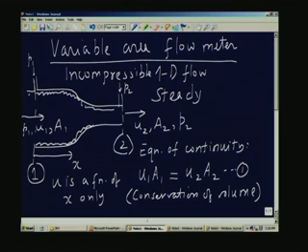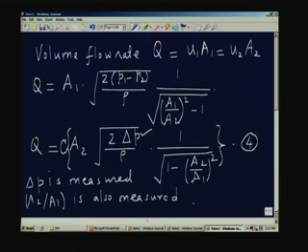So, viscous effect will be confined to the boundary. It can be shown from fluid mechanics principles that the pressure which is measured at the wall is equal to the pressure just outside the boundary layer, which is formed next to the boundary, and therefore, the pressure you measure here is exactly the same as the pressure in the bulk of the fluid.